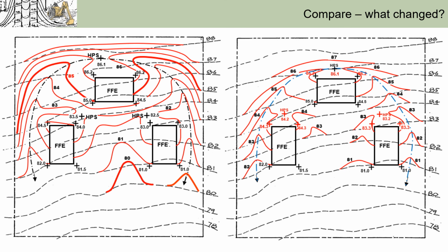Lastly, let's put these two drafts side by side, and you can see that the second draft is not that red anymore. There is much less contour movement here. So iteration is really key to any grading project. It can lead to a major improvement of the quality of the space and significantly reduce construction cost.